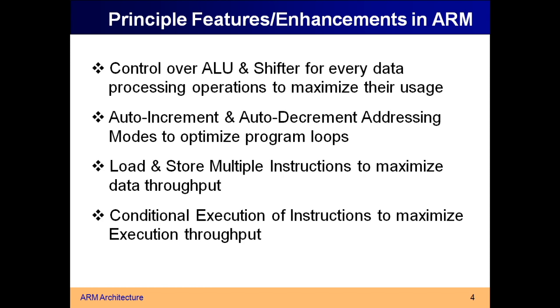But in the case of RISC machine, you can do only single load store, LDR, STR. Here it is LDM, load multiple, and STM, store multiple. And the last feature is you can have conditional execution for all the instructions.